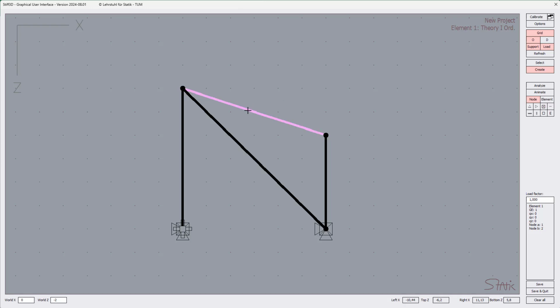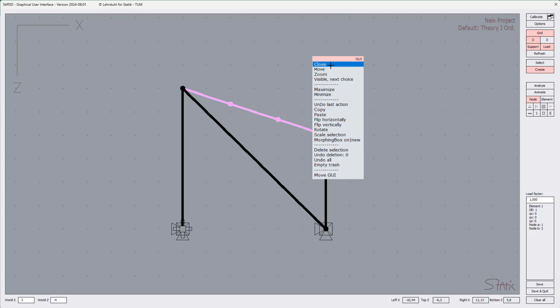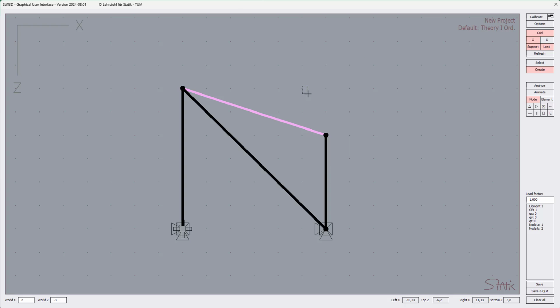By the way, in the split option, if we give an integer number, for instance 3, then this means the element would be split into 3 pieces of the same length. Again, to make it back we can also do it by undo last action. It's the same story. We can also give complete numbers here, calculating numbers.